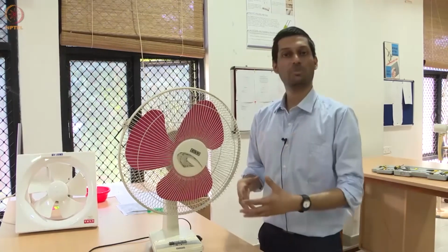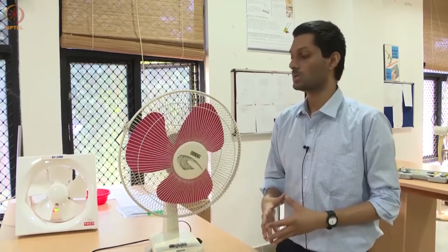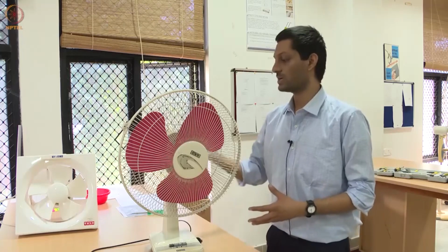In this case, all of the motors used in our homes have a capacitor start and run motor, which means the starting winding is going to be engaged even during operation. In industrial applications, typically they'll disengage the starting winding with a centrifugal switch. Since this is a consumer device, to keep the cost down, we have a simplified system.